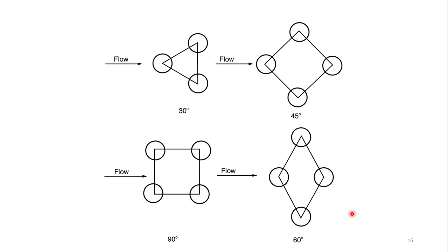So this is a kind of the layout. So these are the 3 tubes, which are basically arranged in the shell and tube heat exchanger. So this angle will be 30 degree. So this is the triangular pitch, and this is the 45 degree pitch, right?